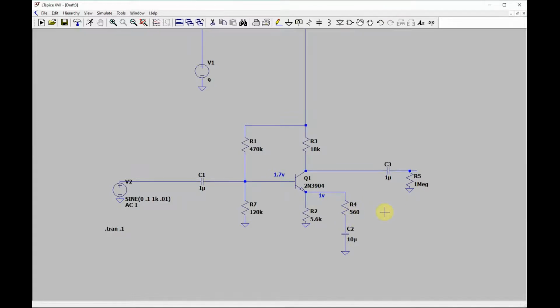Now something happens when you do this, and it may not be obvious to somebody who's a novice. We mentioned that you find the input impedance here by paralleling this and this resistance here. Well, when you bypass this, it changes the resistance across here. So if you get this too low, the input impedance will start dropping.